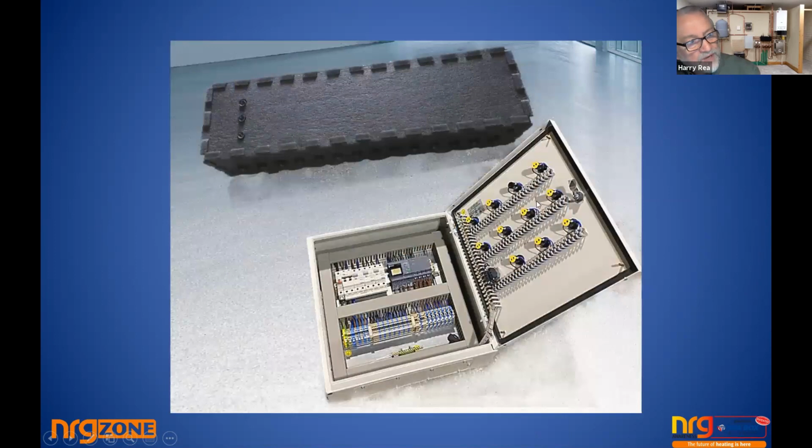And then we do make panels as well. So if you are doing a job, you can make whatever size manifold you want with temperature gauge sensors put in wherever you need them. So for the building management system, we have a flow temperature, we have a return temperature, and we even have a bypass temperature, because there were multiple heat inputs into this device. And then we make the control to suit the job. So instead of the job dictating what you want to do, you can control what you want to do, and it gets rid of all of the hassles of confining yourself to bits and pieces of the normal way to go about it.